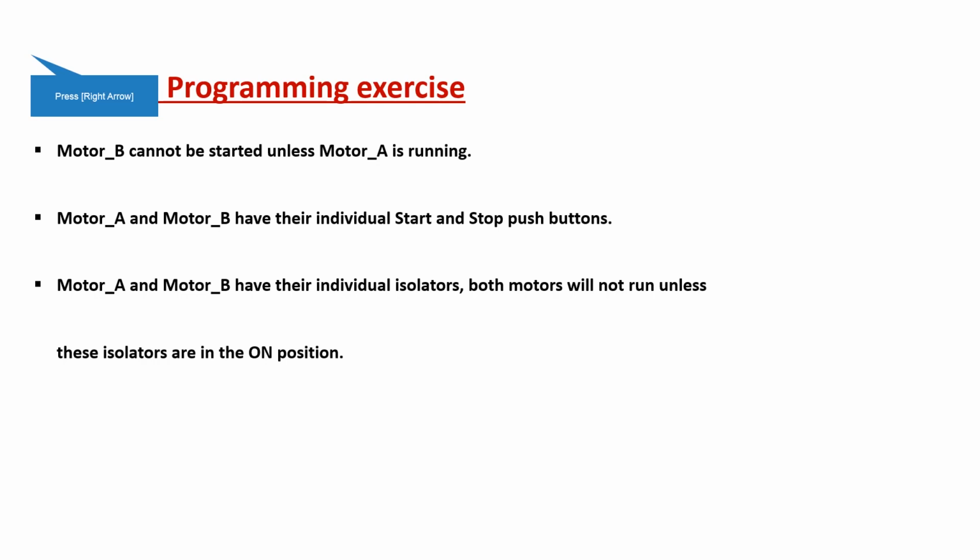Remember, we are assuming a 24 volt PLC, in this case VDC, and even the inputs to the PLC are 24 volts, and the output is also 24 volts. But the relay itself must be able to handle the contacts. They must be able to handle, I don't want to say high voltage, 230, 380 volts AC. I'm not sure whether you're following this.